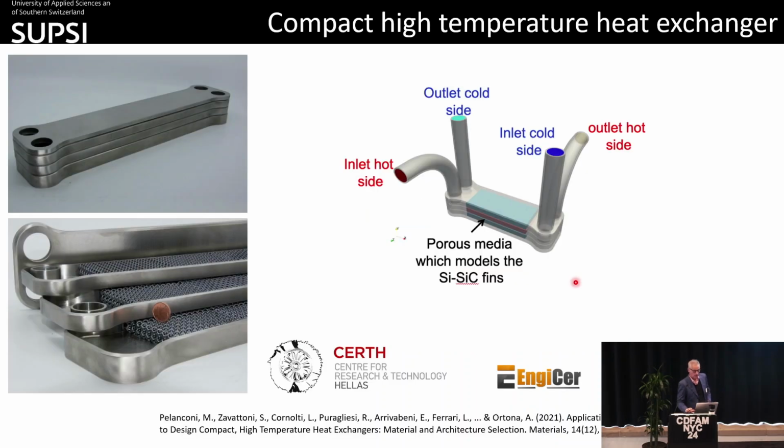Another application is a heat exchanger for using a temperature to recover heat from a concentrated solar panel. In this case, we were using a porous body inside here. This is a plate, something like a plate and fin heat exchanger, very compact, and it was used in a project called Hydrosol